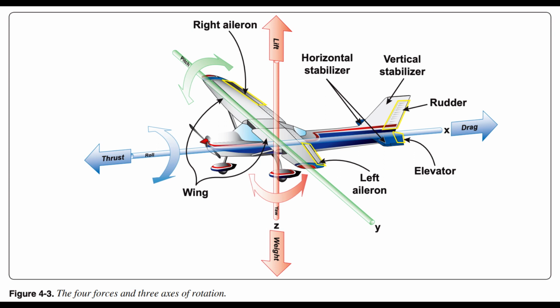Drag is the net aerodynamic force parallel to the relative wind and is generally a sum of two components, induced drag and parasite drag. Induced drag. Induced drag is caused from the creation of lift and increases with AOA. Therefore, if the wing is not producing lift, induced drag is zero. Conversely, induced drag decreases with airspeed.